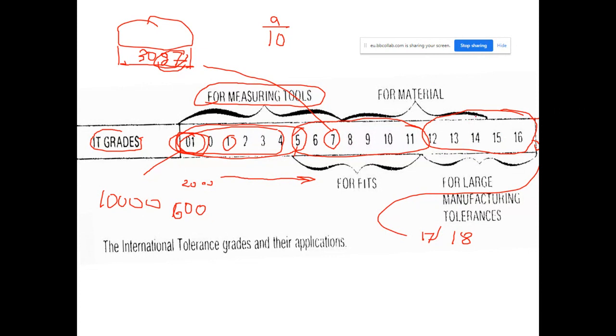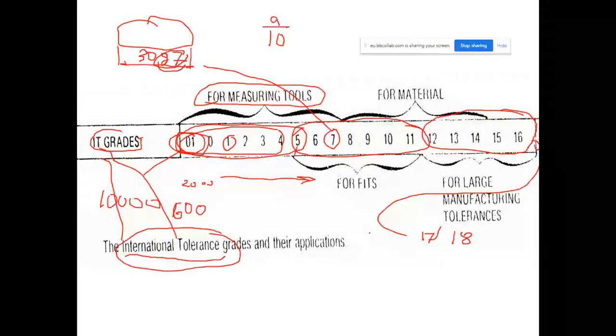Talking about how the upper and lower limits, and thereafter the tolerance of functional dimensions, are determined, I'm going to explain a little bit in detail. These are the IT grade numbers. IT comes from this phrase, International Tolerance Grade System. We generate this abbreviation from this phrase. According to the ISO definition, it is the grading system.